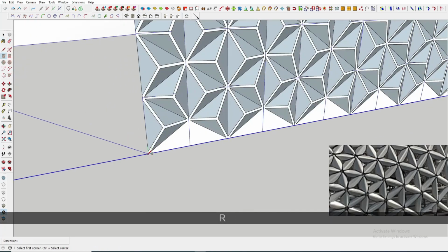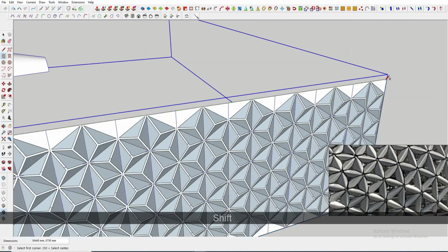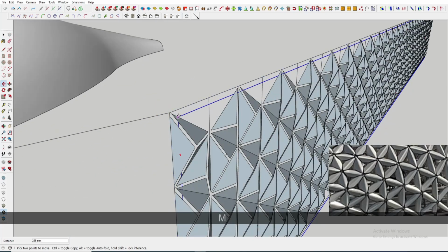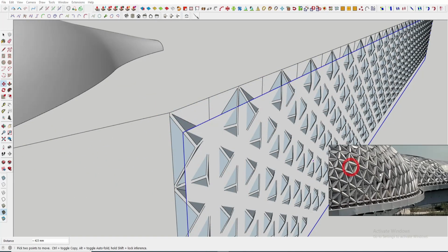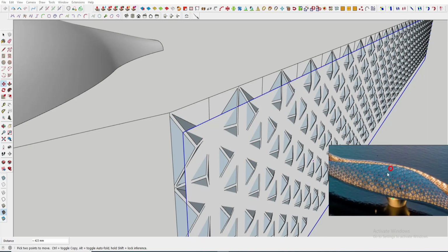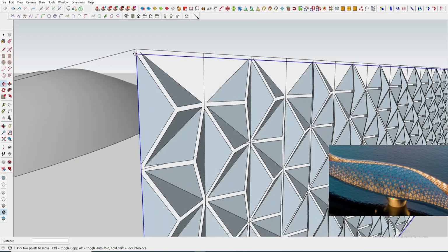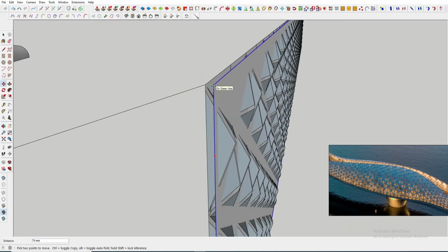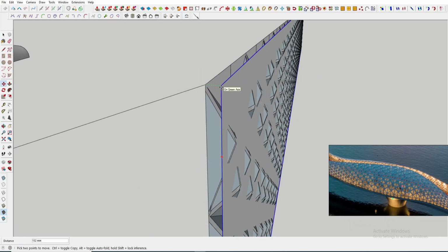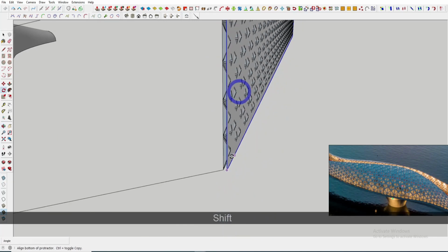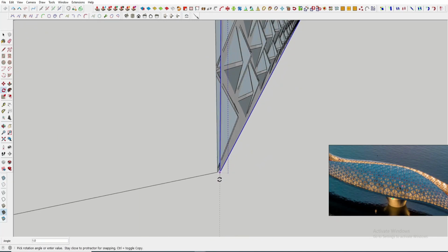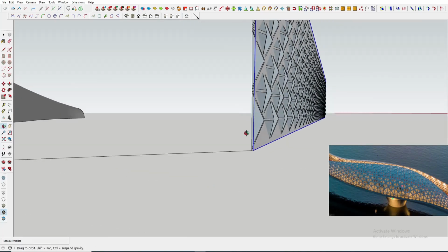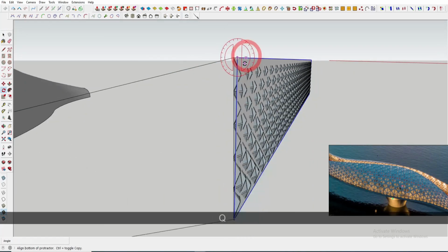So we'll update in the overall component automatically. So I'm creating the surface to create a parametric opening here. So I am aligning on the bottom edge. Actually, if you see, it will be higher openings and the top edge will be less opening. So this plane I'm just tilting up, so we can get that same kind of profile in the elevation.